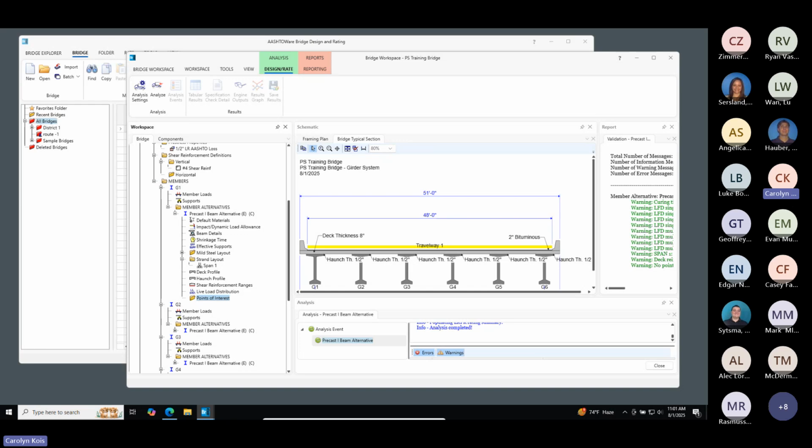On the prestress I-beam input under the properties tab, can you explain the selection box used under section properties and how the analysis option, line girder or 3D FEM, impacts what section properties are used in the analysis?